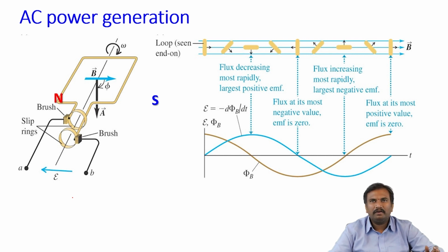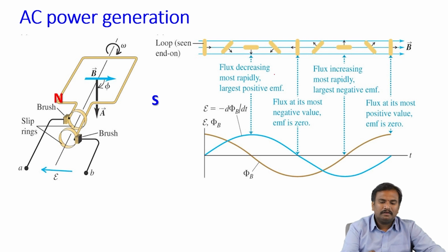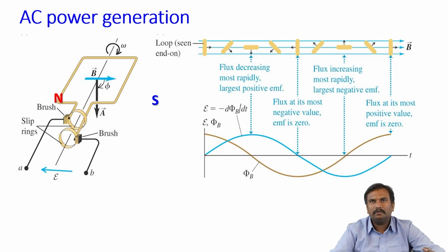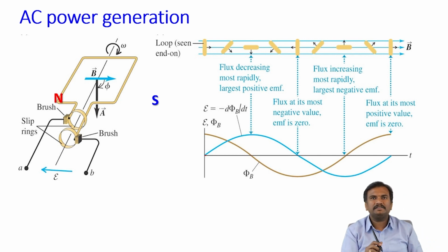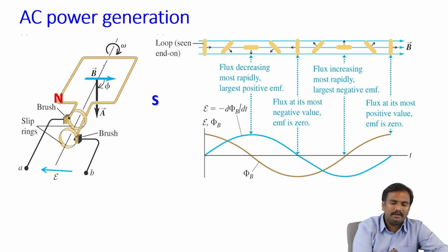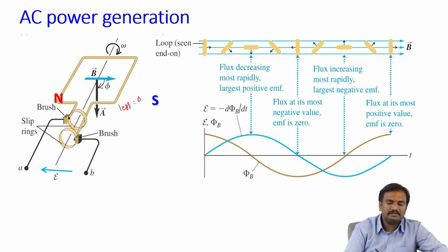As we change the conductor positions, at this position the voltage induced is zero, because when the conductors are placed vertically, the flux cutting by the conductors is less. So the EMF is less.